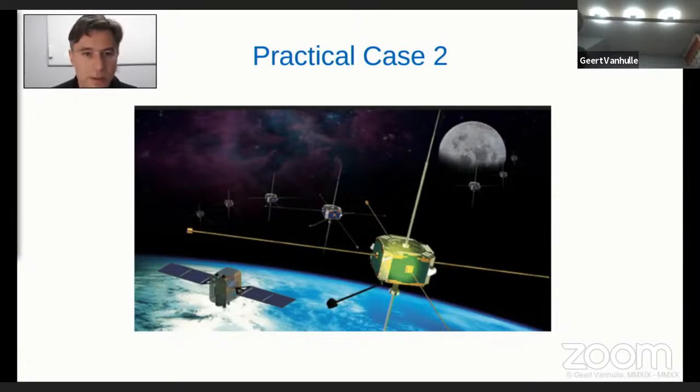There are some spurious signals from this new constellation that enter the receiving side between the satellites. Actually, this could be resolved very easily. It could be as easy as putting a notch filter at the entrance of the receiver to reduce this disturbing signal from the received signal, and the problem is solved.